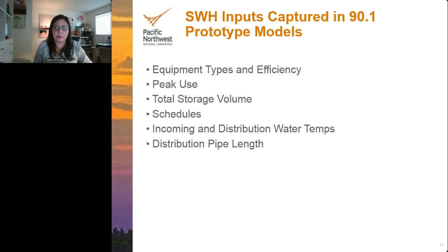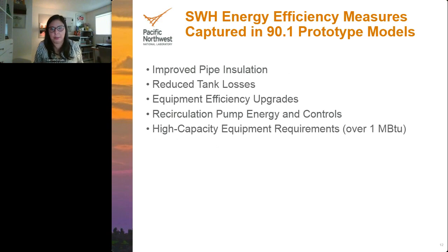So temperatures, there's an algorithm that calculates the groundwater temperature, what we have to heat the water up, and then also the water that goes out to the system. So one of the comments that Jim had made regarding that endpoint, are you waiting a long time for the hot water? So that is an input that we capture in the models, as well as distribution piping. So some of the prototypes, which I will show you here in a minute, do not have distribution per se. They're really more of a point of use, but some of them do have large distribution systems with recirculation. So that's all included.